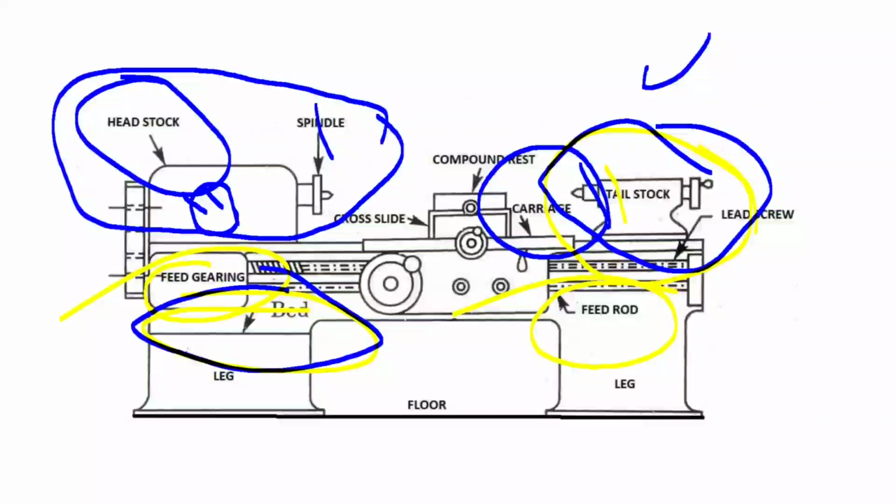It consists of a pair of half nuts which are capable of moving in or out of mesh with the lead screw. The two halves of the nut are connected in the cam slot in a circular disc with the help of two pins. When the disc is rotated by the hand lever attached to it, the pins are guided in the cam slot. These pins open or close the split nuts and hence engage and disengage with the lead screw. Is it clear?